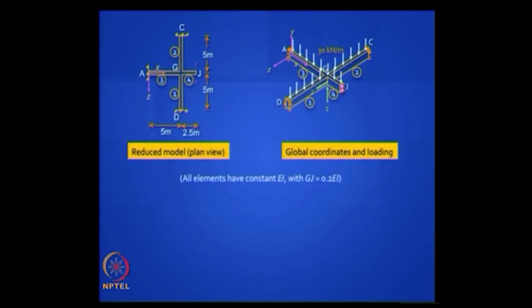If you show the load and write down the degrees of freedom, you will find that you would normally take 3 active degrees of freedom at that common joint G, but you need to take only 2, because we have just established that there is not going to be any rotation along the axis AJ, the x axis, because of symmetry. Is it clear? There is no rotation about that axis, because that would mean twisting of that element at G. Is it clear? So you have to intelligently minimize your work by assigning coordinates carefully.